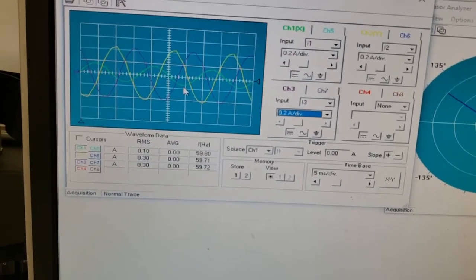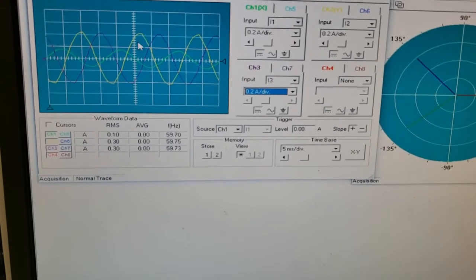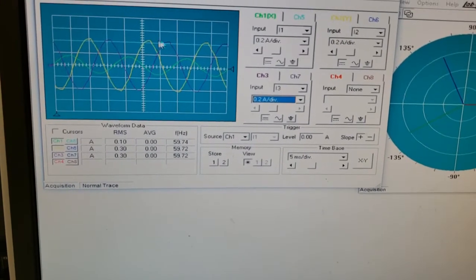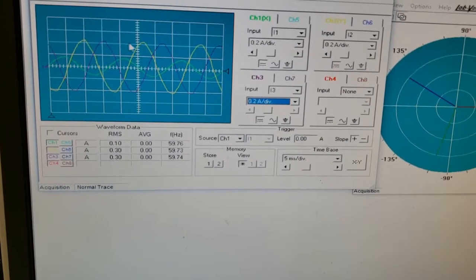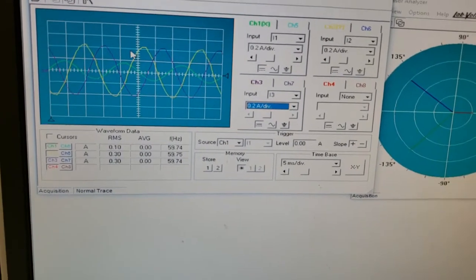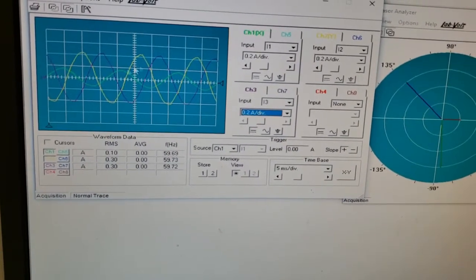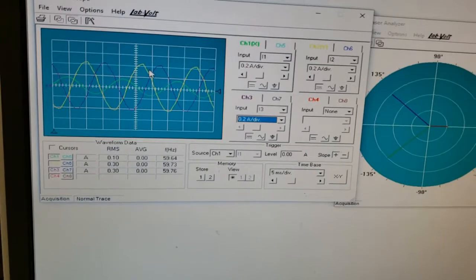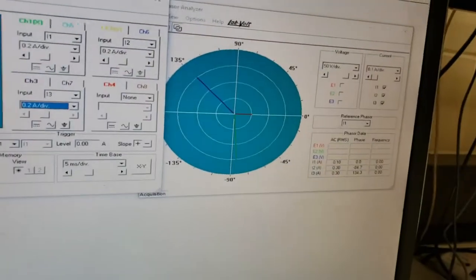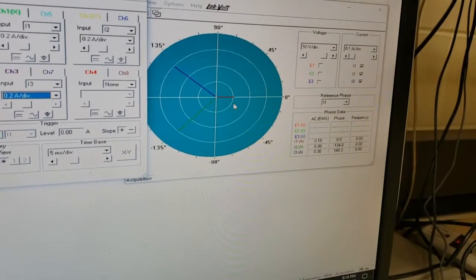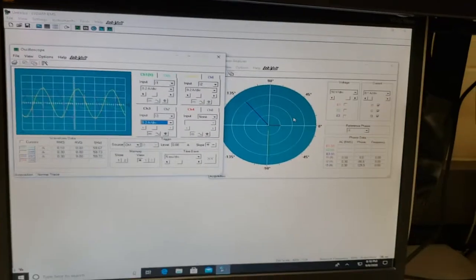Look at that. First of all, no longer three-phase. Clearly, you can see I guess it's hard to tell, but you can see this phase difference is a little less, is smaller than the phase difference between here and here, these two peaks. So the phases are no longer 120 degrees apart. Also, the magnitudes are not the same anymore. This is a lot smaller than these, and those two things violate the requirement to call something three-phase. You can see the phasor diagram is going absolutely bonkers. It's just all over the place. But yeah, anyway, so that's just what happens when you have an unbalanced load.